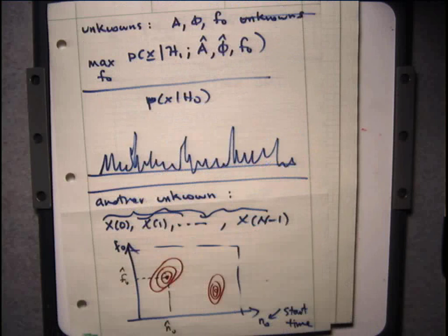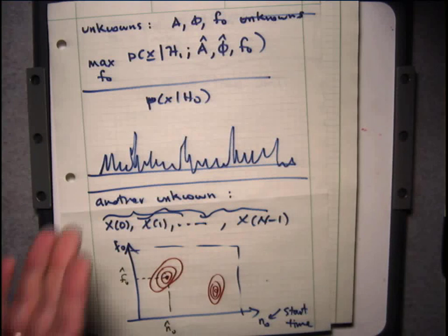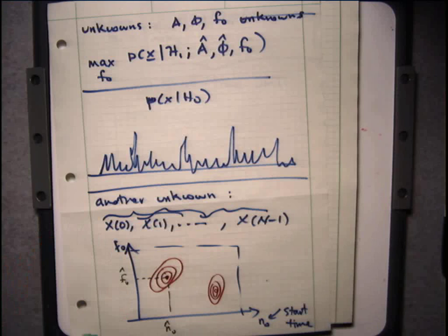How would you generalize this to wavelet decomposition? Well, the wavelet decomposition is just using a different transform. So the idea is, if your signal is here, we're assuming that the signal is a cosine, right? What's the best way to represent a cosine in a Fourier transform basis? Okay, because you get a single number, you get a single coefficient that tells you that signal is present.